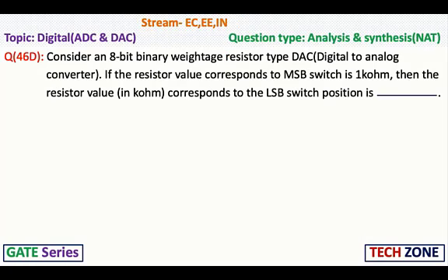And the question here is, consider an 8-bit binary weighted resistor type DAC (digital to analog converter). If the resistor value corresponding to the MSB switch is 1 kilo ohm, then the resistor value (in kilo ohm) corresponding to the LSB switch position is, fill in the blanks.